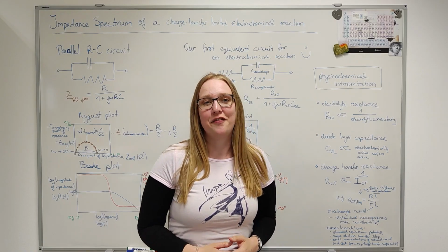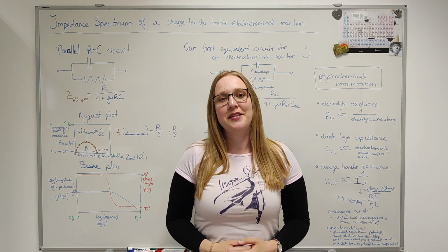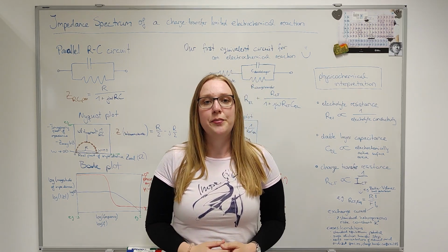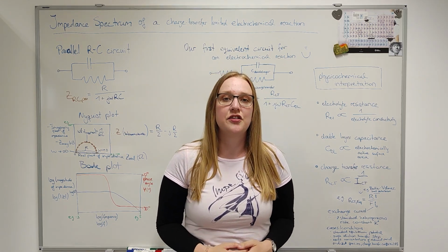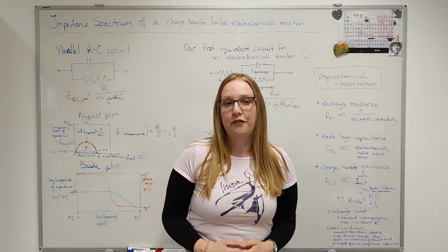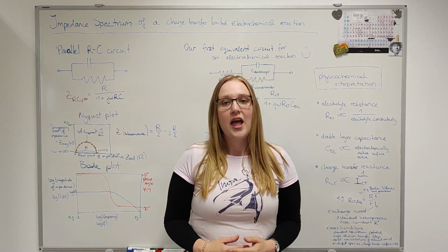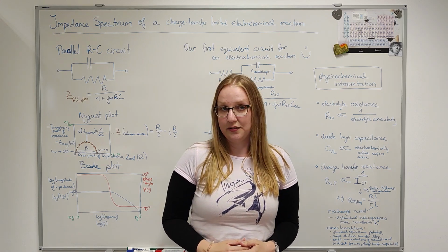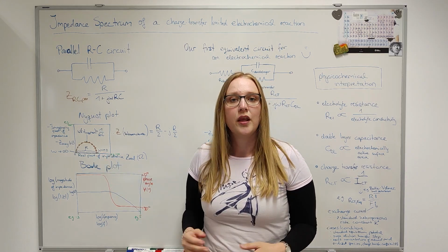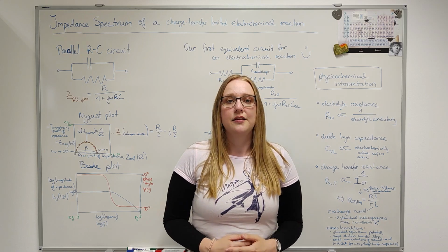As we reached our season finale, we will summarize today's episode just now. First, we looked at what happens if we combine a capacitor and a resistor in parallel. To sketch and understand the impedance spectrum, we make our life easier by looking at certain frequencies where the calculation simplifies. Towards infinite angular frequency, the magnitude of the impedance approaches 0, and the phase angle approaches minus 90 degrees. For an angular frequency of 0, that is direct voltage, the impedance simplifies to the resistance with no imaginary part. The phase angle is 0 degrees.